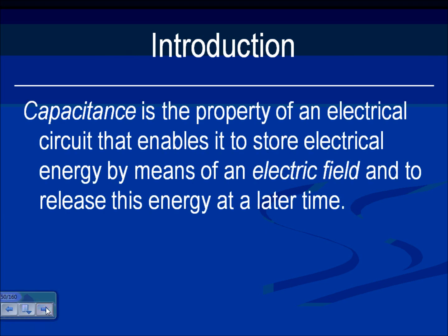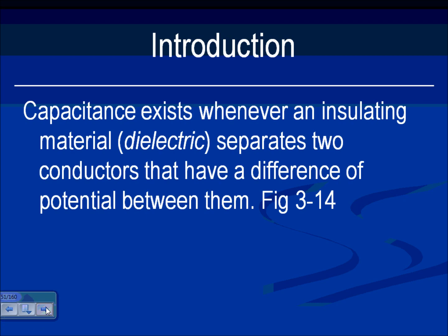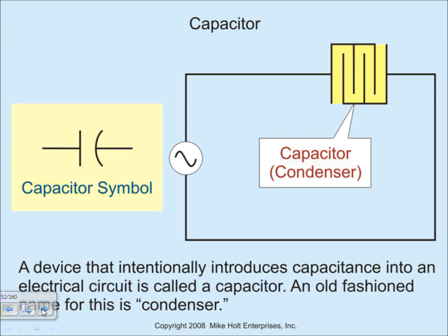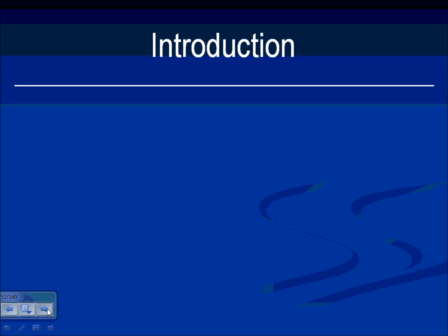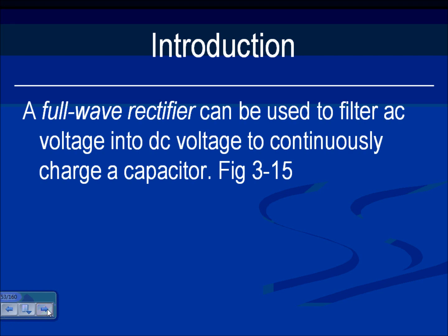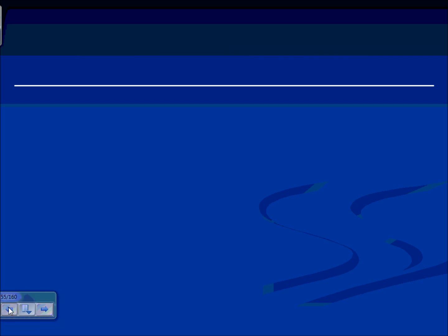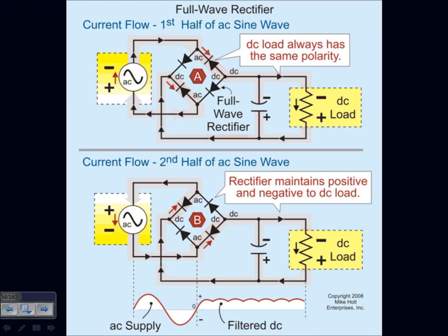All right, capacitor. Let's go to the capacitors. A few things about capacitors, guys, to remember from a power point of view. Capacitors always make a leading power factor, so the current will lead the voltage. There are a couple of applications for capacitors in the power industry.